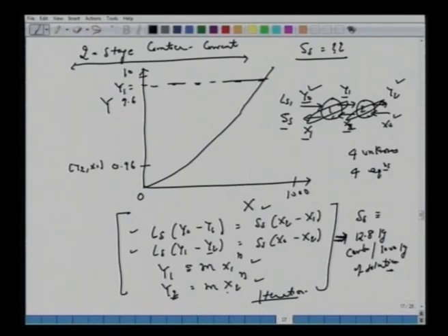All we know is there are two stages. So if we know the amount of the solvent, of course, we can draw a line like this, which has a positive slope for countercurrent. This should be equal to SS over LS. But we do not know SS. That means we require iterations. Let's say we have made a good guess that for this y0, this concentration must be x1.